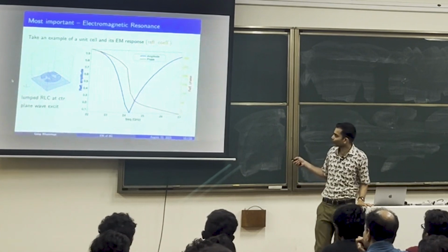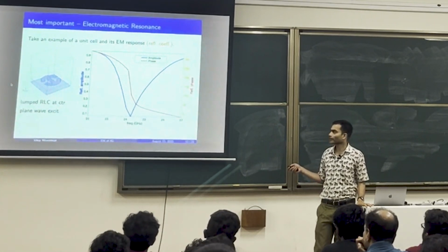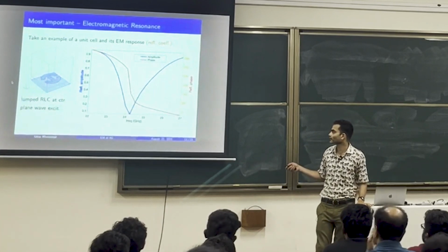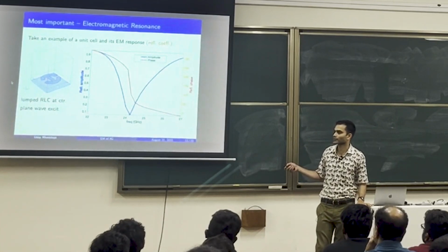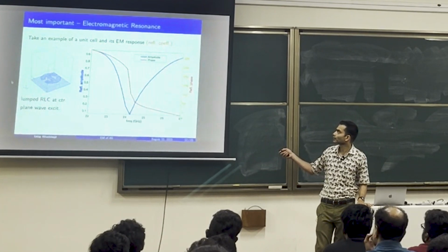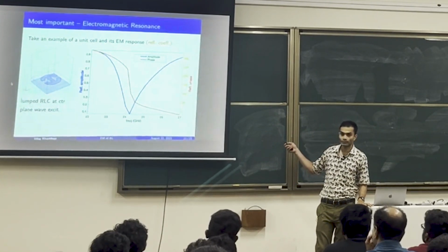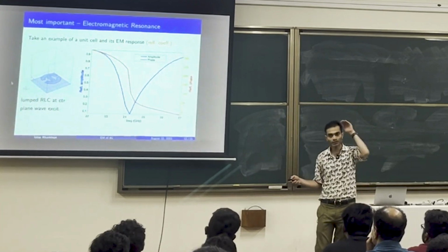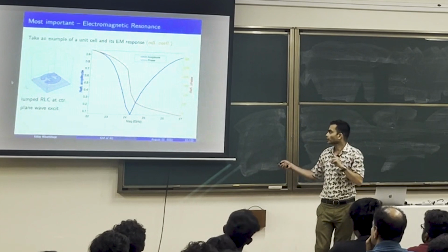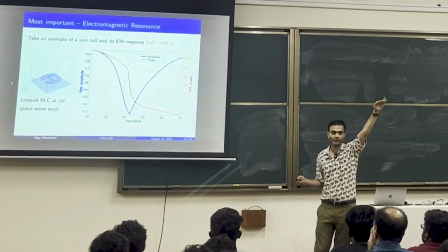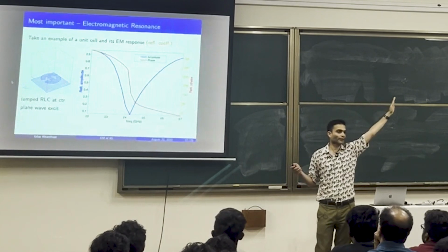So, what are the main things I want to get from this graph? If I were much less in frequency, let's say at 22 gigahertz, 21 gigahertz and so on, the reflection phase looks to be how much? About 330 degrees. And if you draw this curve further, this red line sort of flattens. It just becomes flat. So less than 24 gigahertz, the reflection phase is always 330 degrees. Nothing else is happening there.